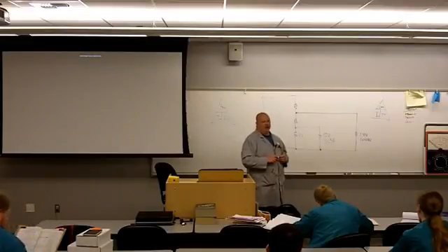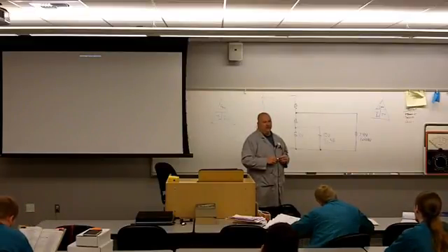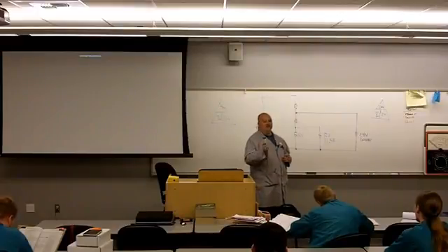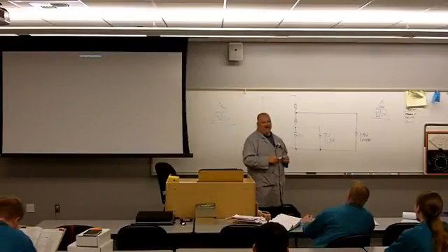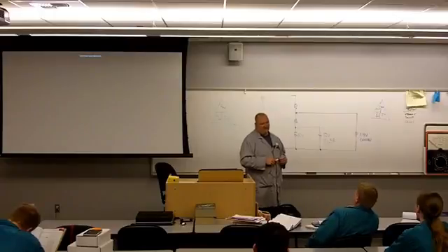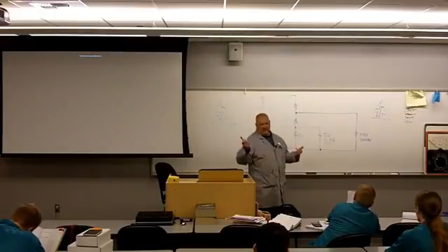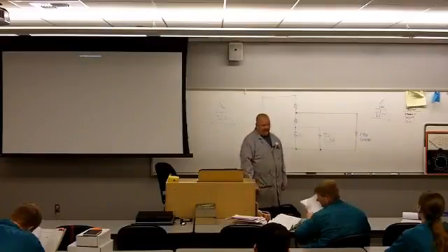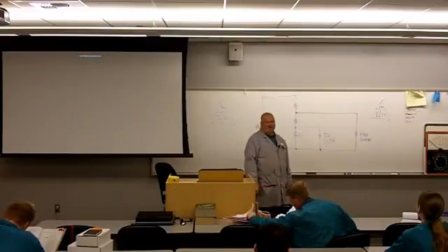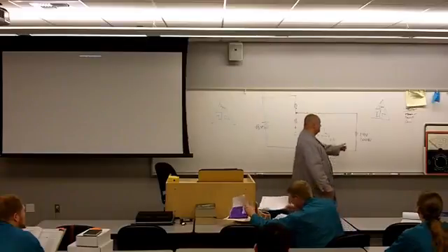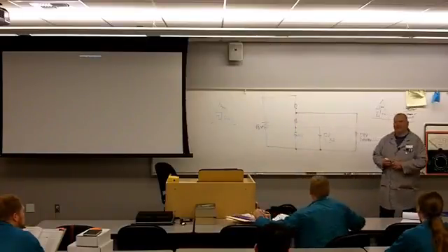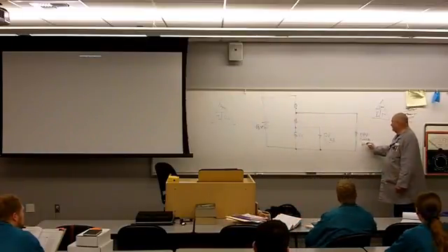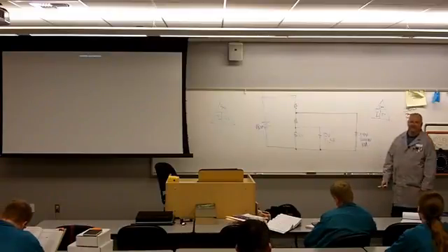8.33, and that assumes what? That assumes 100% efficiency. Do we get 100% efficiency out of this stuff? To be honest with you, if we're lucky, if some of this stuff operates at 80% efficiency, 20% of the energy gets consumed as heat. Okay, so just for the case of example, I'm going to say that this thing really, in order to work properly, is going to need 10 amps.